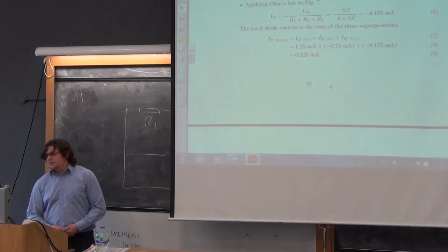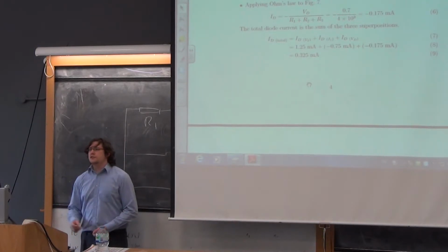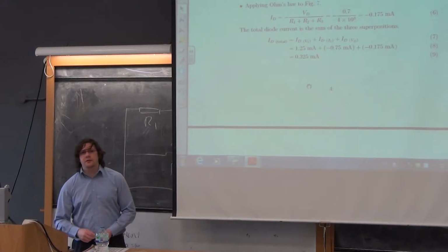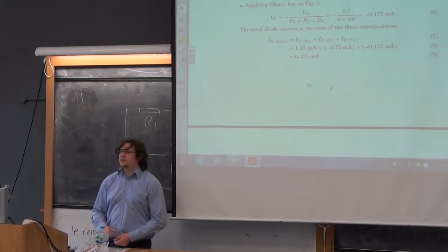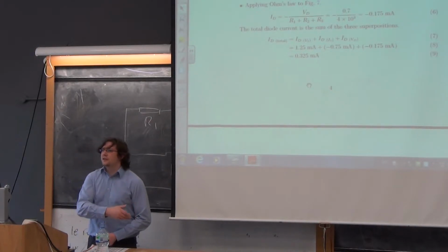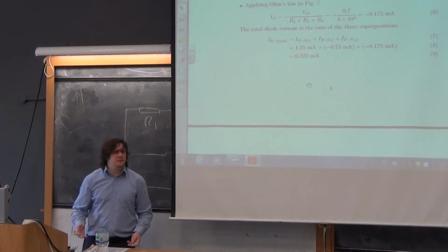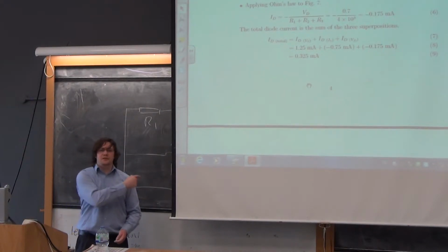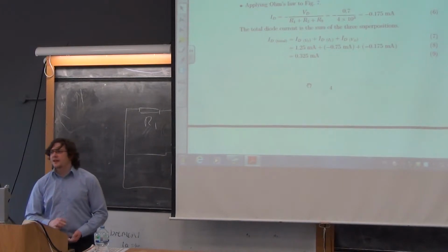So the adding up is equation A. Now, I knew this diode was conducting because I wrote the question. You will not have known the diode is conducting. So before you do this bit of analysis, you have to do the bit of analysis that says, I assume the diode is not conducting. I just stepped in and solved it. The reason is it's nearly 11:15 and we've got to get on.